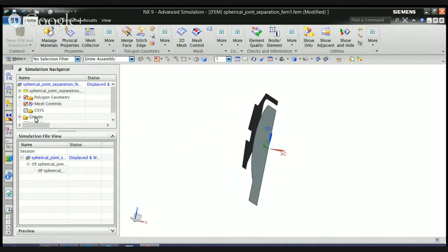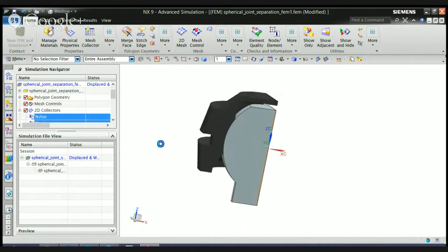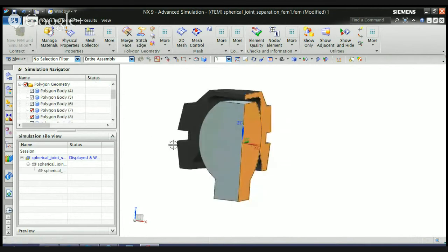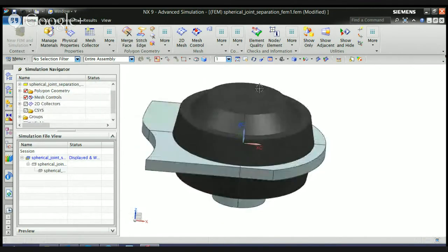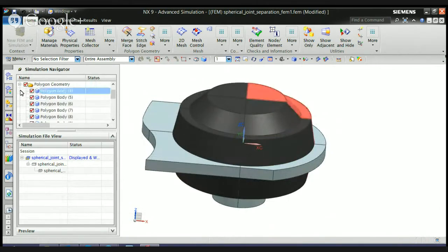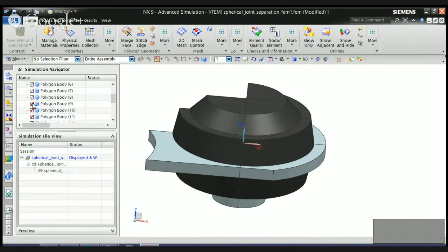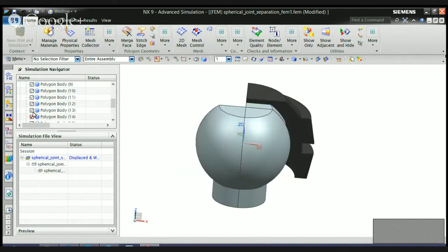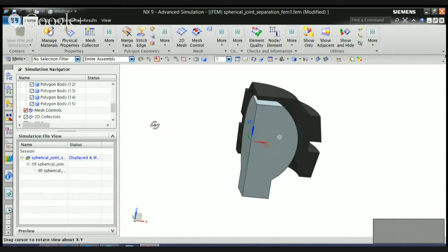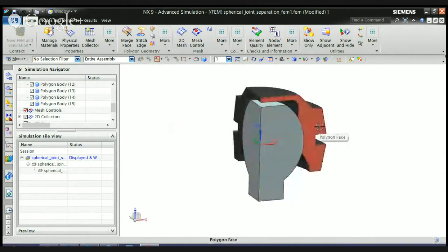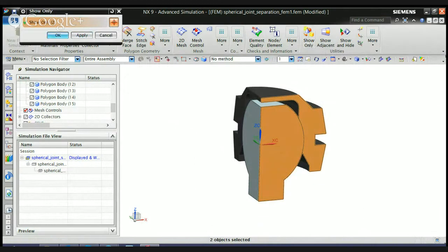So I actually made a big mistake. What mistake did I make? Whatever I selected, I actually have to keep these two components on the ZX plane only. Don't keep the components on other planes. So I'm switching, I need the first three. Now I need the ZX plane components only, not the other components. So now these two components I can select. I can say show only.